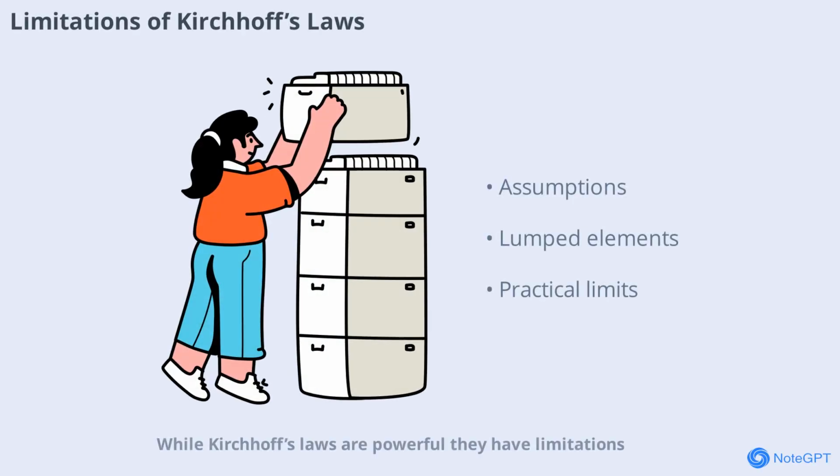While Kirchhoff's laws are powerful, they have limitations. They assume that the circuit elements are lumped and that electromagnetic effects like capacitance and inductance are negligible. In high-frequency or very large circuits, more advanced analysis methods may be needed. However, for most practical circuits, Kirchhoff's laws work perfectly.